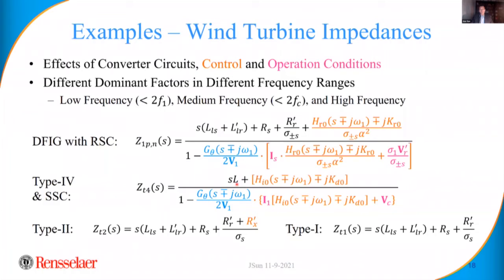It's the inductor impedance. The second term here corresponds to the current compensator. So what this equation tells you is that current control of a converter is equivalent to adding a series impedance, right? So your proportional gain in the current controller is effectively a resistor.